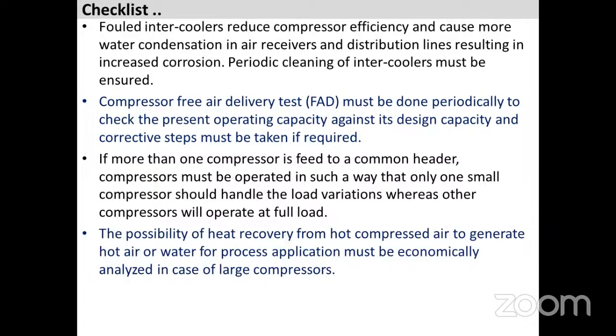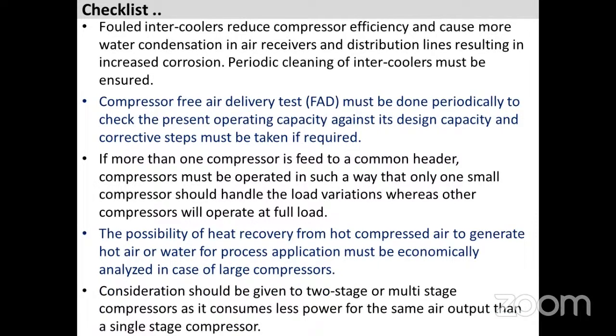Possibility of heat recovery from hot compressed air to generate hot air or water for process application must be economically analyzed. This is all for big compressors. That is recovery from the compressed air, and that hot water can be used for some processes. Just one more point: consideration should be given to 2-stage instead of single stage.